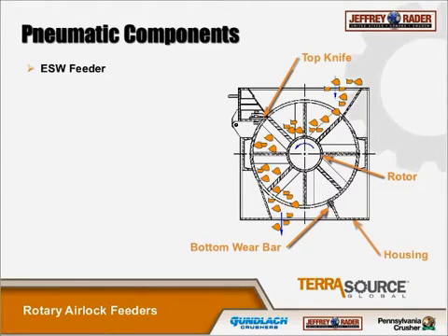The industrial housing, as we said just a second ago, is chrome-plated. That is able to extend the wear life of the feeder, also provides corrosion resistance. The rotor and housing are machined to very tight tolerances, and this allows us to minimize the air leakage from the feeder, and that's taken into account when choosing the blower.